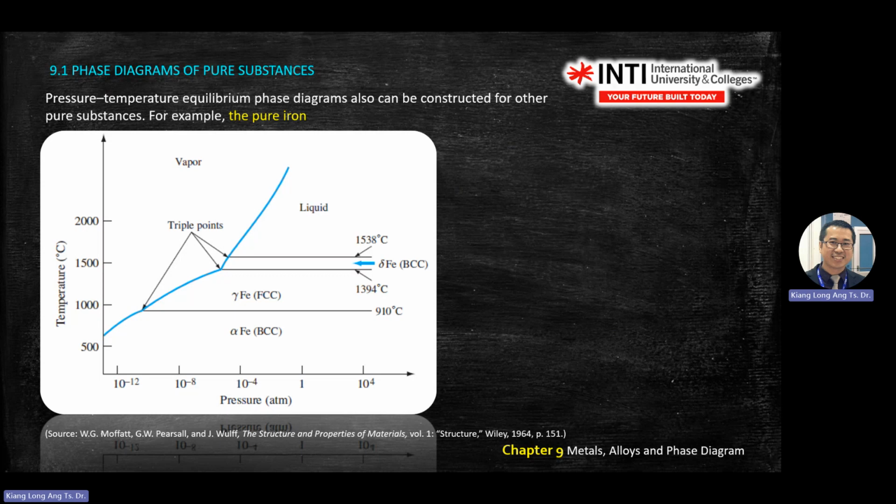For metal, if you see a name like alpha copper or alpha ferrum or gamma something, that is solid. If you see liquid, it is liquid. Vapor, vapor. If you see a scientific name, then it's a solid phase. For example, delta ferrum is a solid phase. So all these lines, you should be able to understand what they mean. And this straight black line also represents a phase.